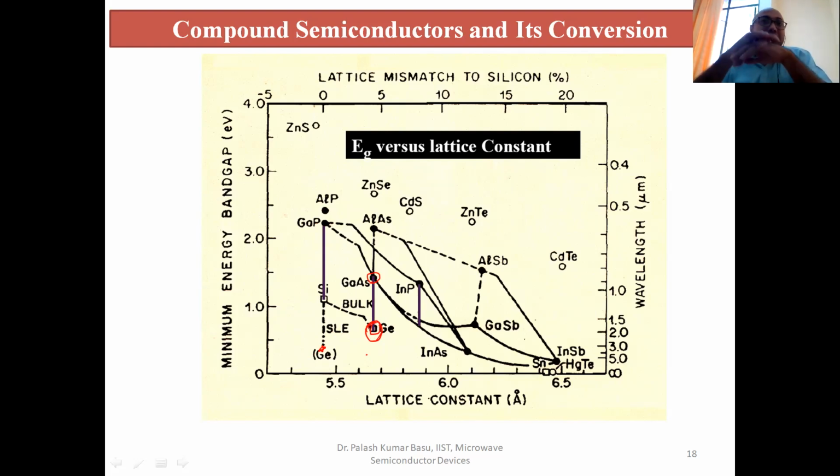So this curve is actually very important for us, and this is one of the things we have to really remember. You cannot deposit your material randomly on any substrate. You have to go back, check different papers and literature, and if you want to deposit gallium arsenide or some other material on a particular substrate, you have to find out the crystal structure and other parameters like surface roughness. We will look at these at the end of this course when we discuss fabrication. But this is very important.